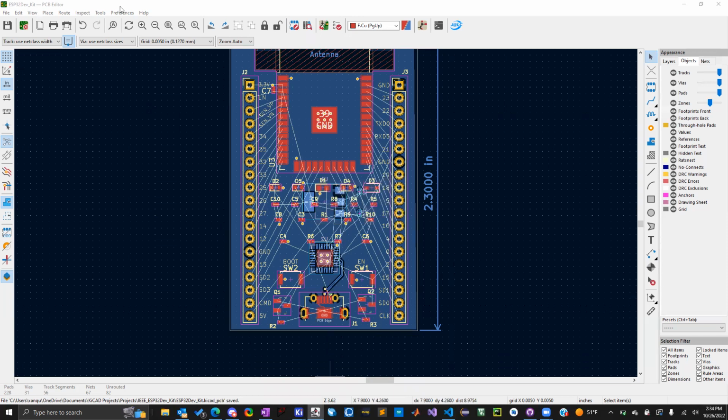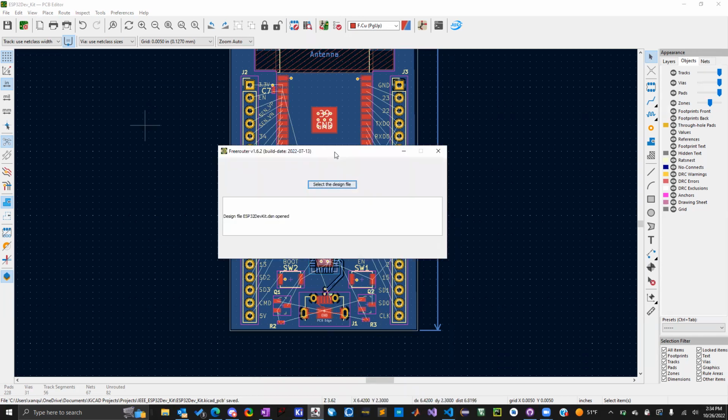And you should get this pop-up. Did you not install it, or is there issues? Oh, okay. You can still auto route it just to see how it works if you want to mess around with it a bit. But whatever work you did, when you strip all the tracks, it'll remove the vias too. So you would have to redo the vias. So I understand if you don't want to do it.